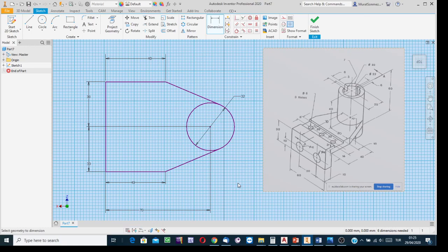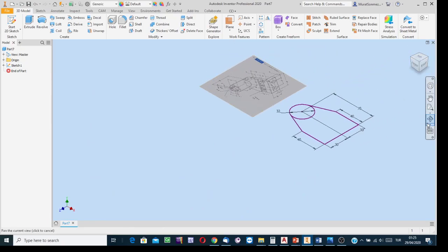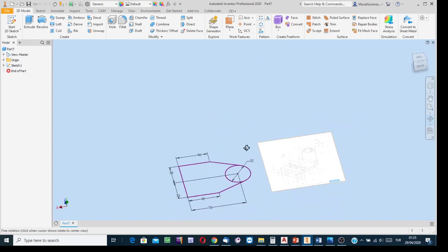Yes, that is it. Now, this is the profile to use for creating the model of this part, and we can also use this sketch, indicating the profile bounded by the circle, to create this cylindrical extension in the up direction, and a cylindrical extension in the down direction. This is not cutting, it is the adding method. Okay, finish the sketching stage. And then apply the extrusion process.